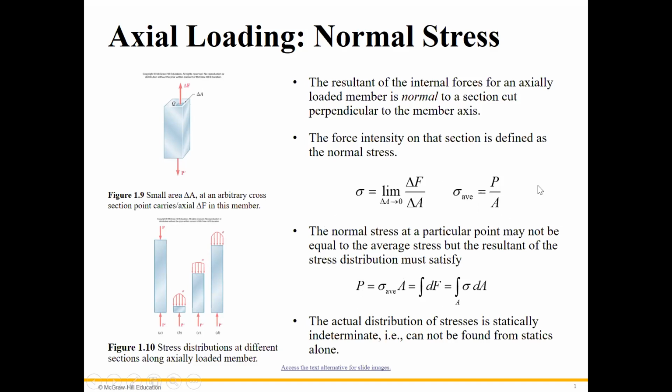So I want to say this is some definitions of that. You can see all this formula, but the only thing we need is just here, and we can also ignore this index. So the stress based on the actual loading would be just P divided by A. Now just assume, in the example from the last lecture, if I give you the cross sections for each element, it's easy.